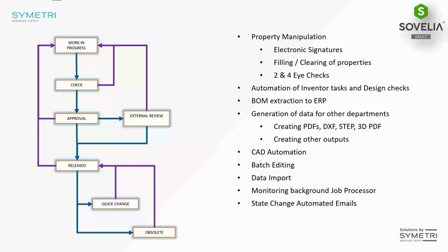That property can then be mapped back to, say, something like a revision table. So you're kind of working with electronic signatures here to a certain extent. You're ensuring that the username is written to a property, and that property could be written to something else, whether it's part of your data exports or part of a drawing list. Again, that property is automatically filled in.